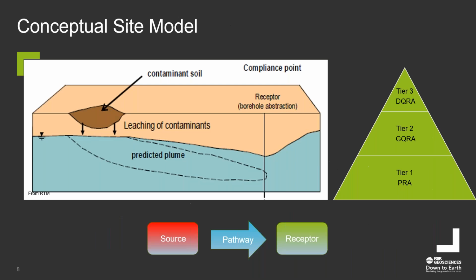Conceptual site model. Before starting the groundwater remediation, it is essential to develop an appropriate conceptual site model, as always we do. The LCRM defines the CSM, the conceptual site model, as the representation of the characteristics of the site in a diagrammatic or written form that shows the possible relationships between contaminant sources, pathways, and receptors. A series of investigations, such as boreholes, trial pits, collection of soil and groundwater for laboratory testing, maybe geophysics, LIF investigation, NAPL mobility assessment, etc.